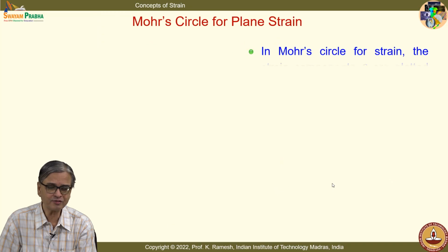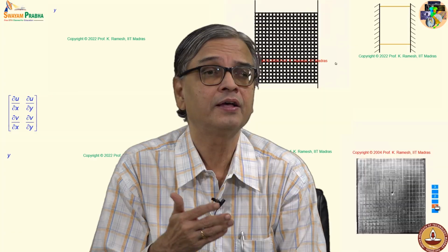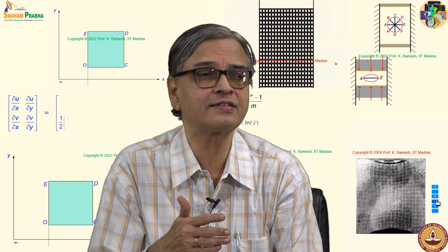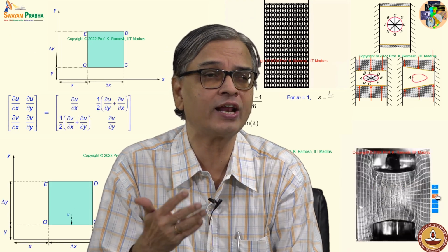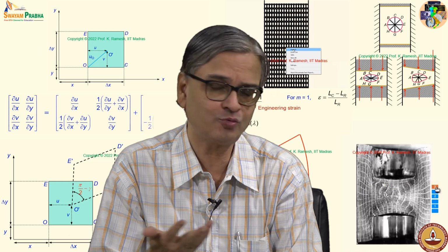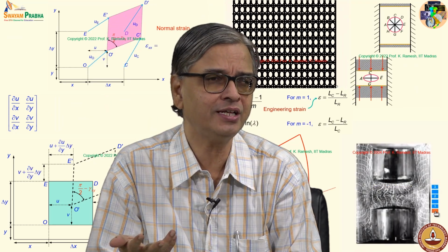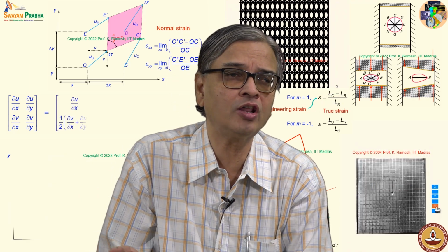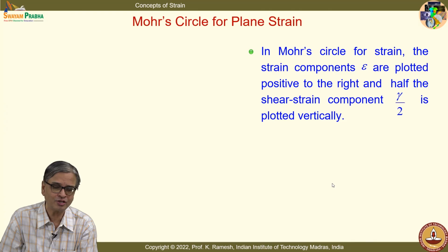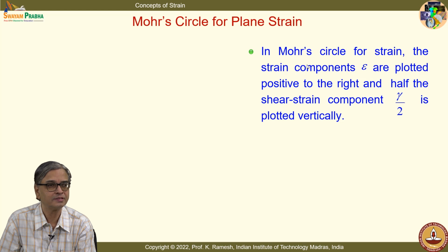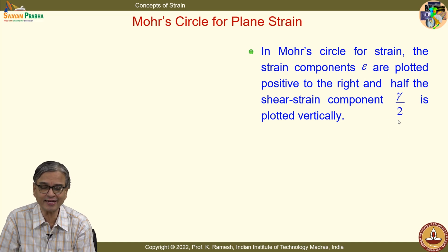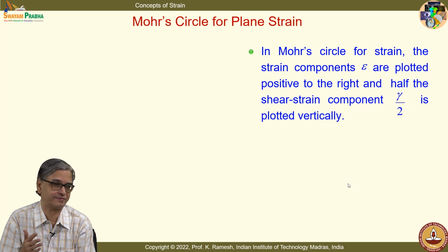And when you develop these quantities, you also need to know, if I change the frame of reference, how do I express or get these quantities? That is what you do in stress transformation or strain transformation. Same thing, if you do it for all the possible directions, you have a Mohr circle. And I have said, historically people developed shear strain as gamma, but tensorially it is only gamma by 2 that behaves.